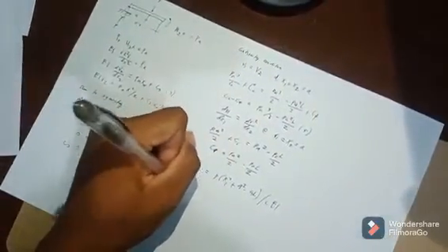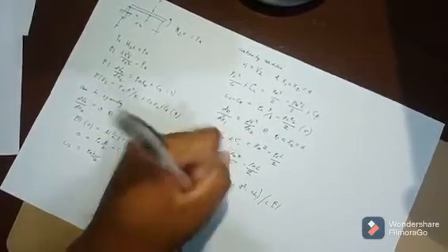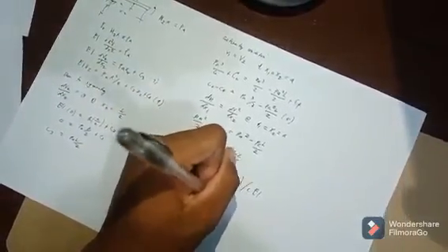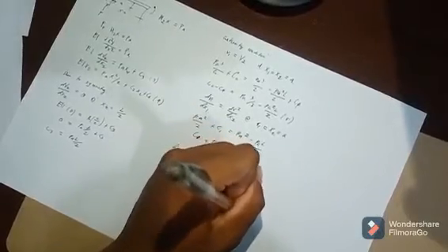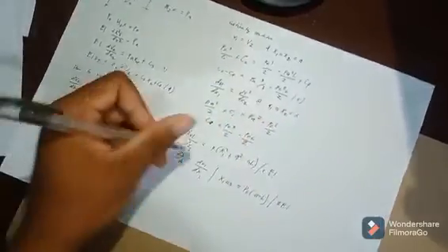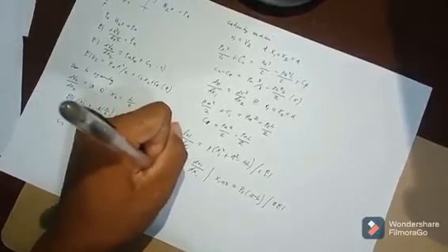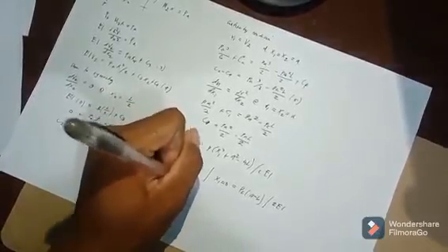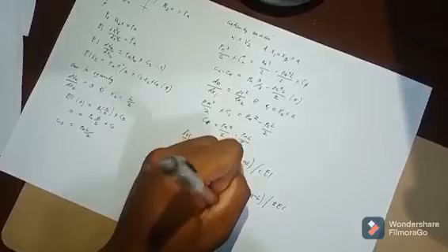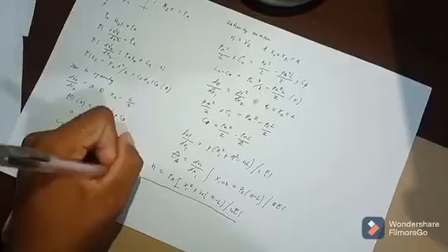So the change in slope at A is equal to dv1 divided by dx, at x sub 1 equal to 0, is equal to PA times a minus L, over 2 EI. Solving for v1, it is equal to P times x sub 1 squared plus 3a times a minus L, divided by 6 EI. So this is for the v sub 1.